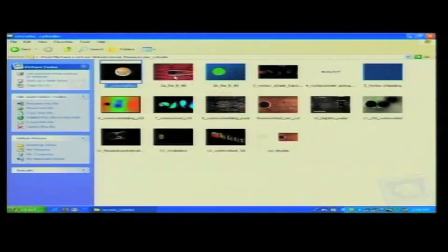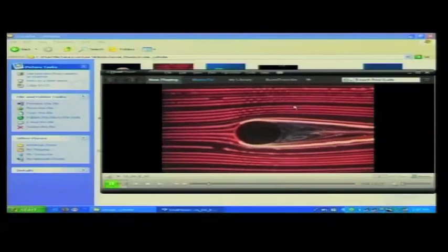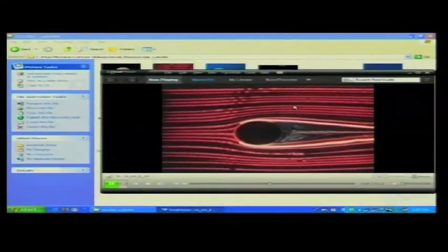Now, if you increase the Reynolds number, what happens? Let us say the Reynolds number is increased beyond, say, 4 or something like that. At very low Reynolds number, the solution is almost like a Stokes flow solution. So, the solution does not consider the advection terms on the left hand side of the Navier-Stokes equation. The advection effects are totally neglected in that solution, but in reality the advection terms may be important, typically as you go far downstream.